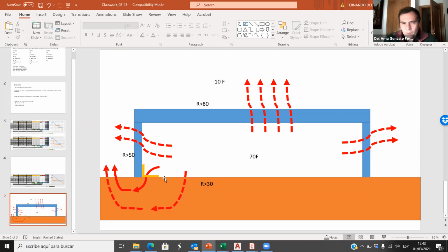And most of the floors that you will find are uninsulated, so they don't have any thermal insulation. There's a reason for that. If we have heat at this point, most of the heat will go either up or through the walls. That's fine. If this heat tries to escape through the floor, it has to go from the indoor to the outdoor.